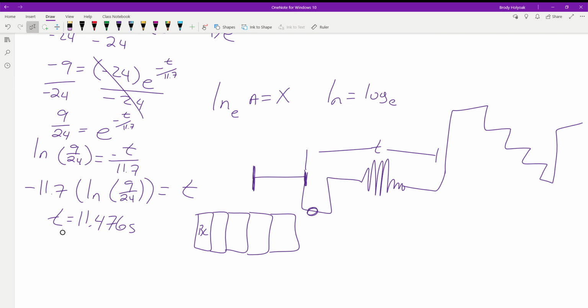So you could have your master signal be delayed by 11 seconds after turning on your equipment to say, okay, now everybody's authorized to move. We have to get my computers warmed up. We have to get everything going. This is quite a bit of delay, but it could be the matter of saving a life. You sound an alarm saying, hey, crap is turned on. You've got 10 seconds to get out of pinch points. You should have more controls in there than just, here's an alarm, get your butt out or you're going to get squished.